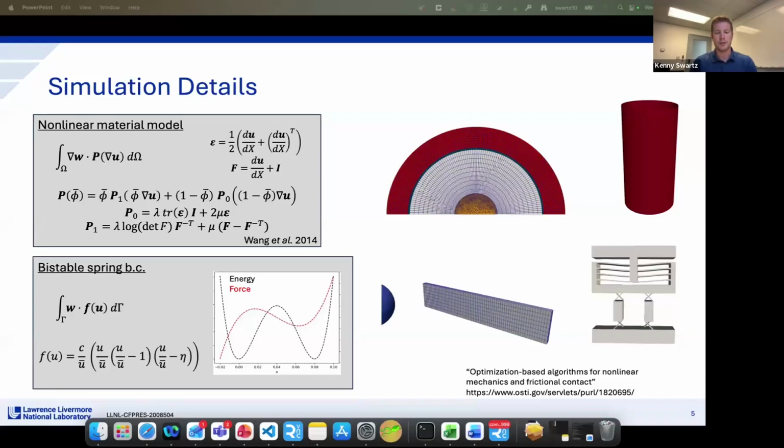And then the second challenge, which comes into this problem, is the fact that we have bistable mechanisms. So we think about these gates, and as I mentioned in the beginning, we're talking about digital mechanical behavior. So we're going to have inputs where we have basically a displacement that comes from some external object that goes between two distinct states. And we're going to model that through a bistable spring that's relatively stiffer than our gate is. And so the input is going to either be snapped into its off or its on position. And so we model that with this fourth order energy curve, which gives us a cubic force displacement. And so when we push on this thing, it'll give us some resistance up to a point, and then it'll kind of snap through to its second configuration.